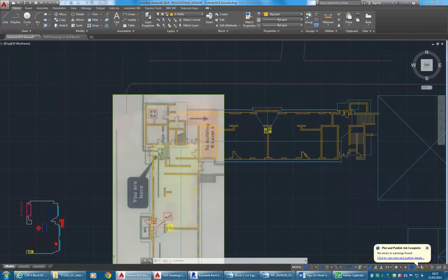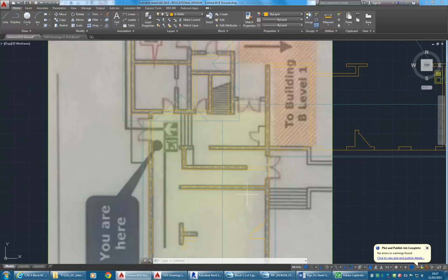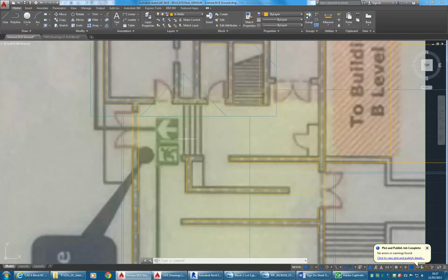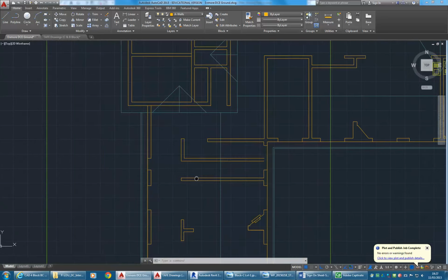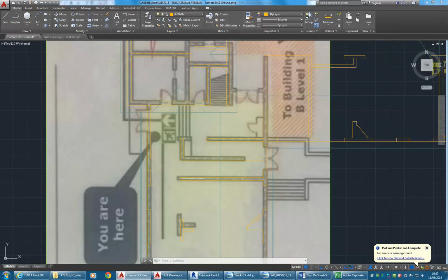Once you have those levels established, then you can start roughing out the ways you're going to get from one level to another using both the stairs and the ramps. I just wanted to give you an idea about the setup of those things, because they're the last major element, apart from your floors and walls and ceilings as well, which I'll look at with the levels. The stairs and ramps are the other major building element that you'd want to be factoring in, probably before you even worry about openings, things like doors and windows. You can worry about those right at the end of all of this setup, and then finally, the more detailed things, skirtings and cornices and all those final things.